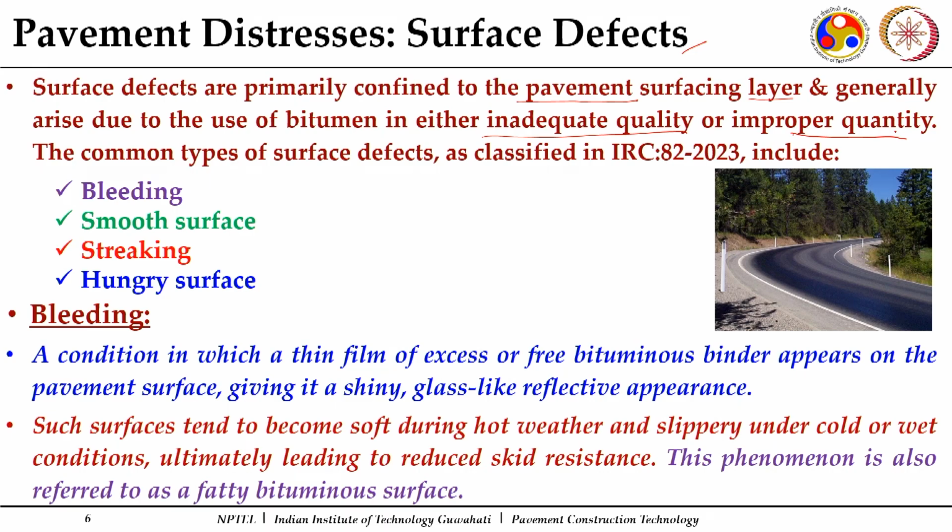So, either the selection of grade is improper at the application of tack coat, where we also select definite grades of emulsions, or the selection of the binder when the bituminous mixes are produced may not be the right grade.